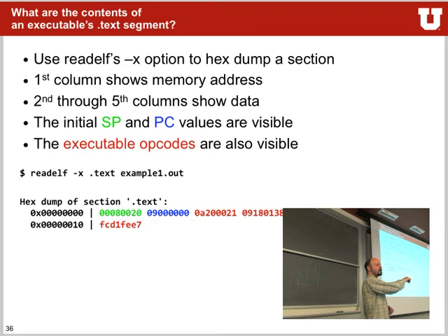It tells us that it's a thumb instruction because it's a 9 and not an 8, but this is the reset vector jump address, right? Like it's the start of where we start off at memory address 8. And that's here. And now if you want to go into details, you could start decoding this using the ARM manual and actually figure out what all the different opcodes are and what they represent as assembly instructions.